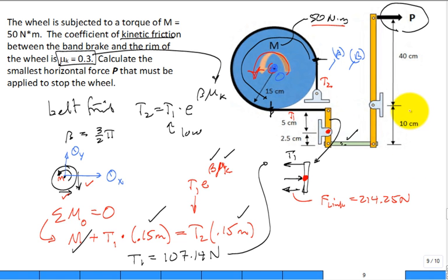Come up here. If I do a free body diagram of this member, what do I have over here? I have P. That's what I'm looking to solve for. Some force at this support. And then we said the force in the link was in what? Compression. So it's pushing that way. That's our force in the link, which we just solved for. Do the sum of the moments around that point, and you'll be able to get that P is equal to 53.6 newtons.